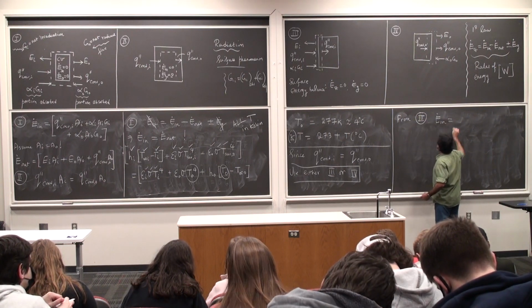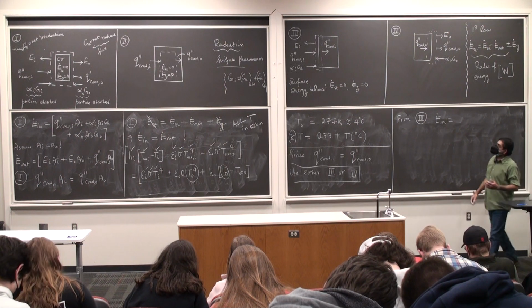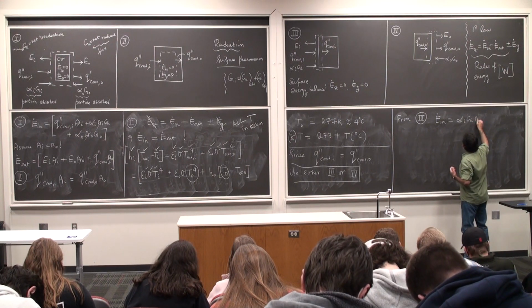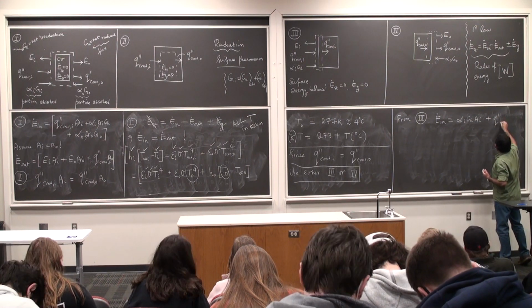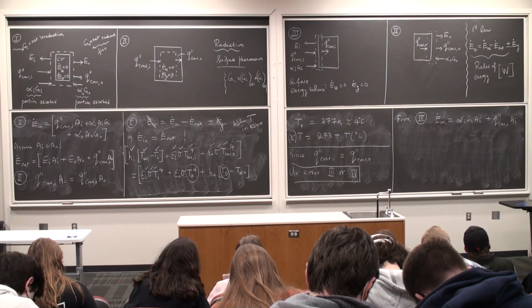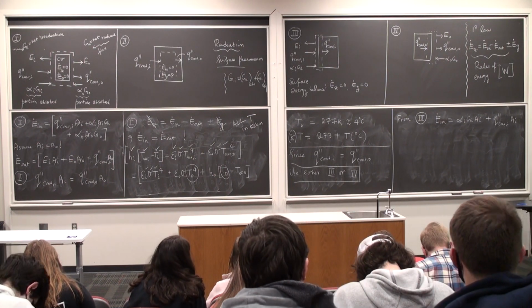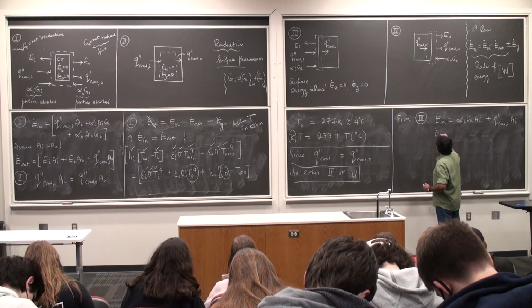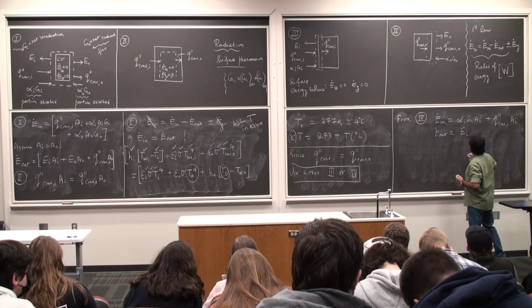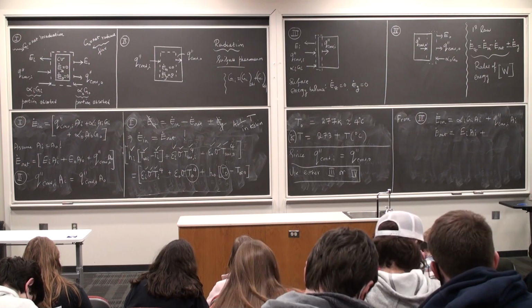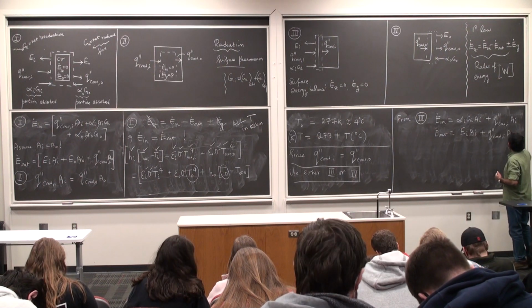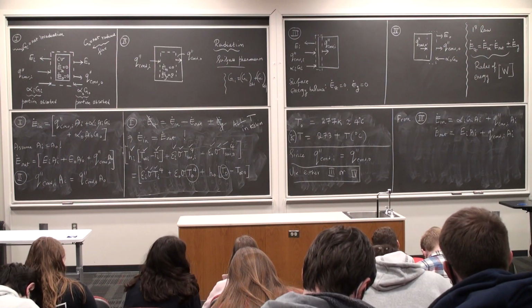E dot in, always use the equation. E dot in is things coming into the control surface, so this is going to be alpha I G I times A I, plus q double prime times A I. E dot out, things moving away from the control surface, which is going to be E I times A I plus q double prime conduction times A I. E dot stored is 0, E dot generated is 0.